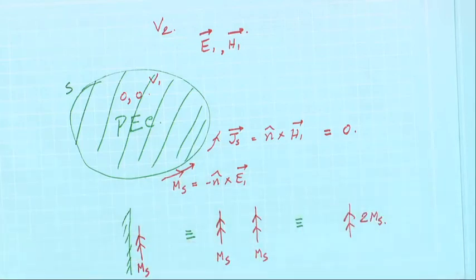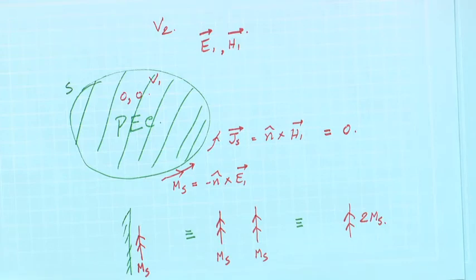Actually, you see that an open ended waveguide, if we think of the waveguide as an antenna, we always make a ground plane along the open ended waveguide. If we assume that ground plane is infinite, how do you assume? In practice, if you take generally 5 lambda for a conductor, that ground plane length in all the directions, then you can say that it is an infinite ground plane. So ultimately you find the current.